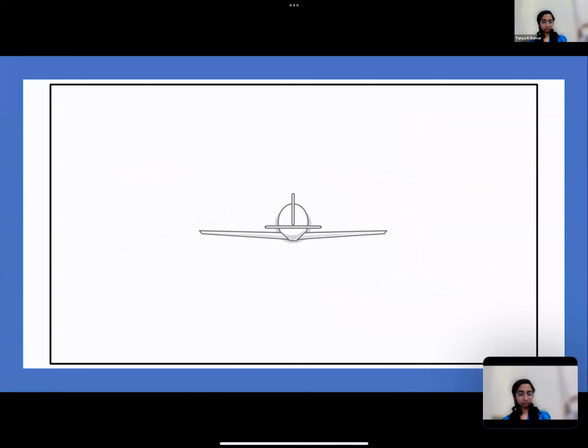Adverse yaw can be prevented by using the rudder to create a yawing moment that helps to turn the aeroplane in the correct direction to remain coordinated. Some aeroplanes incorporate design features to minimise the adverse yaw. One such feature is called differential ailerons. By excessively deflecting the upward aileron, drag is increased on the downgoing wing. This produces a desired yaw force in the direction of the turn.